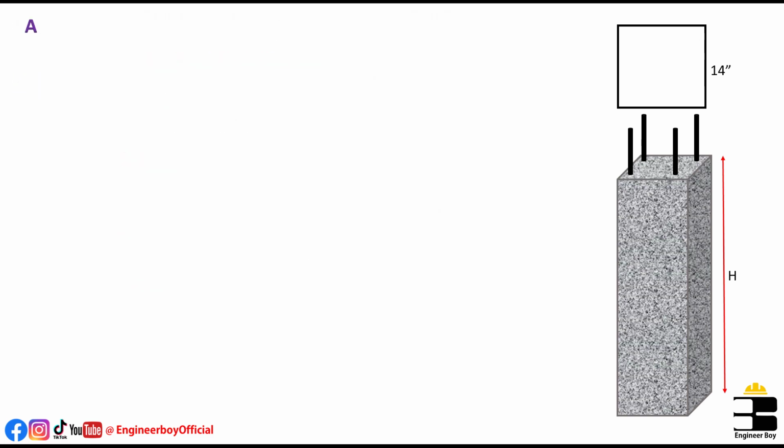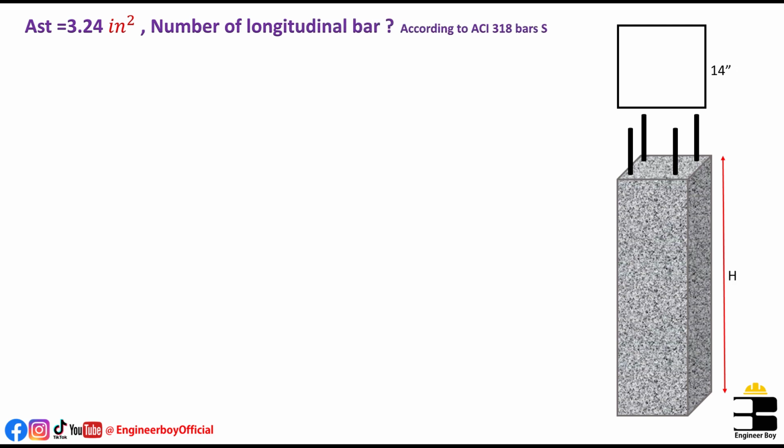Once we have Ast, then we can easily calculate the number of rebars. But make sure the number of rebars should not be less than 4, okay?